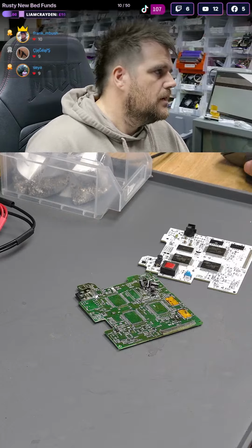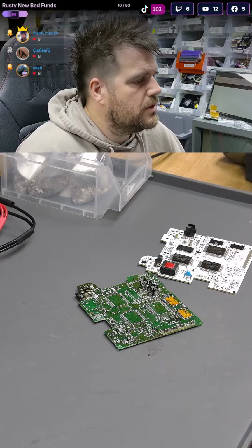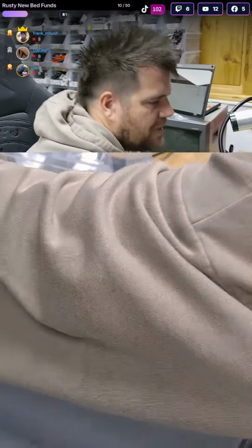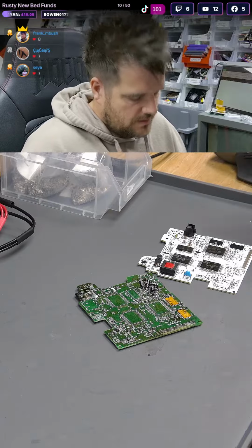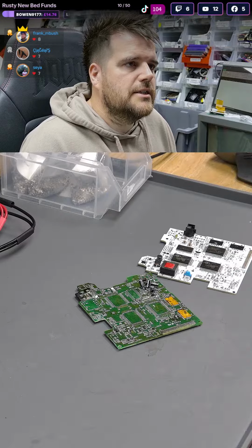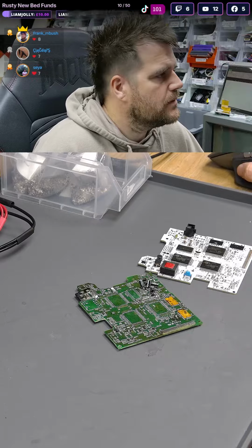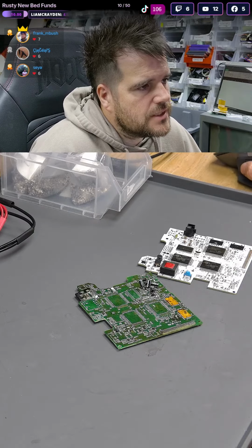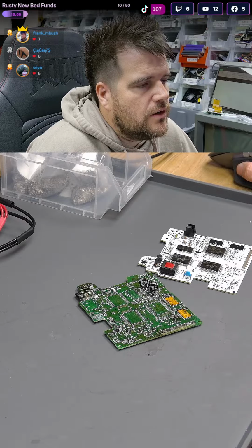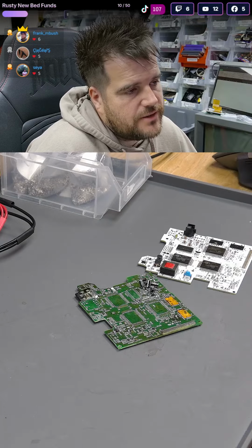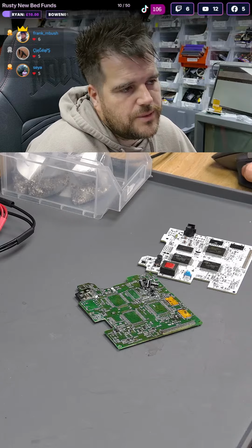boardview-pce.retro6.co.uk. I might just put this down as, for now, the 1.5 nanofarad with a question mark, because other than the tester measuring, you can't be any more accurate. So it'll work at that, but I've got a feeling it's a standard value. Let's have a look at standard capacitor values in nanofarad. At the low end there is a 1.5 nanofarad: there's a 1.2, 1.5, 1.8. So it will be 1.5 nanofarad.